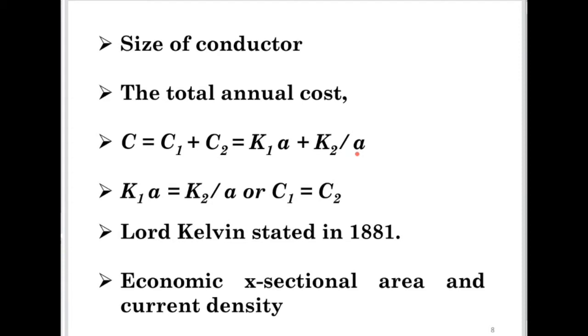So ampere per millimeter squared as well, we can determine, because that current density actually tells us how much heat can be generated because of that power loss or the energy wasted in the line. And we need to make sure that we have an arrangement to ensure that the heat generated is dissipated into the ambient.